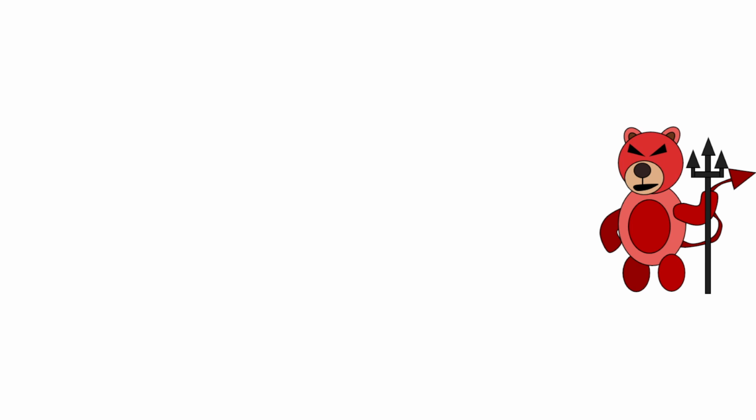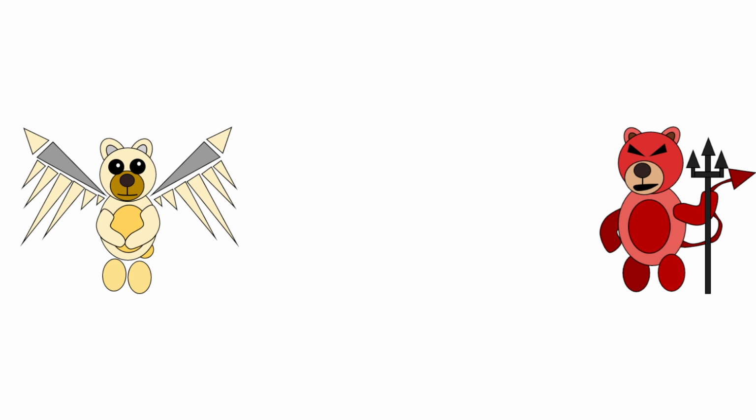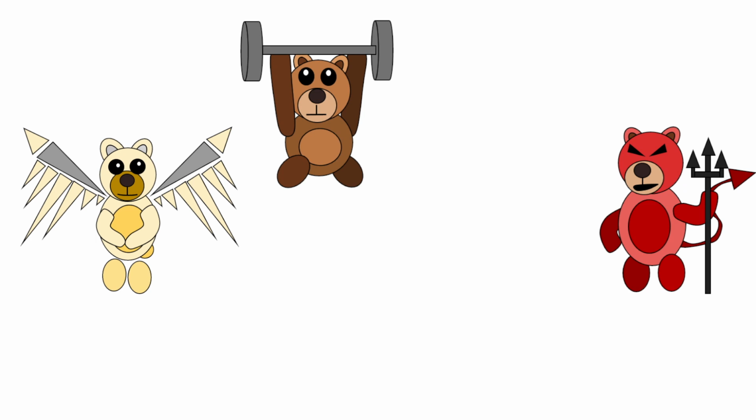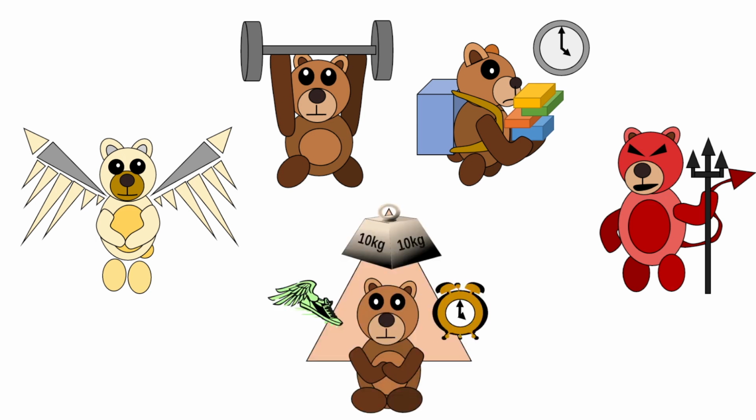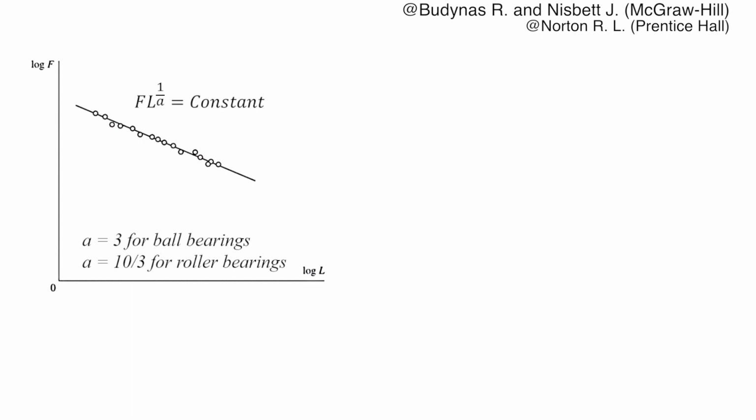Now, most bearings do not start off as bad bearings. Most, in fact, are good and well designed to start with. However, by subjecting a bearing to an excessive load, running the bearing faster or longer than necessary, the bearing will degrade quickly. A good designer must keep in mind the principles with which to select a bearing, balancing performance requirements without breaking the bank. In bearing design, it is well understood that there is a constant relation between bearing life and load placed on a bearing.